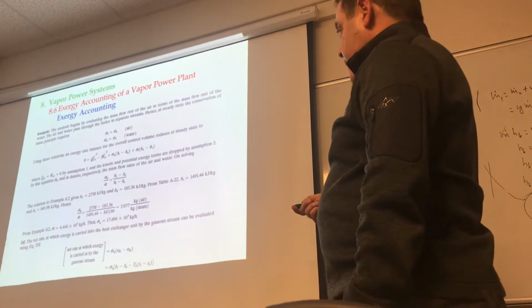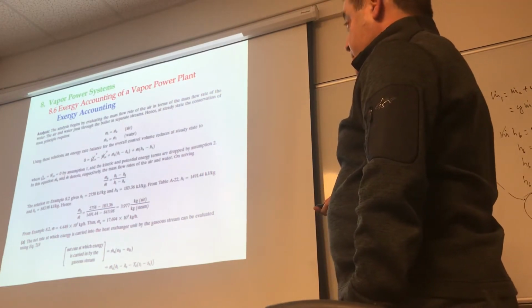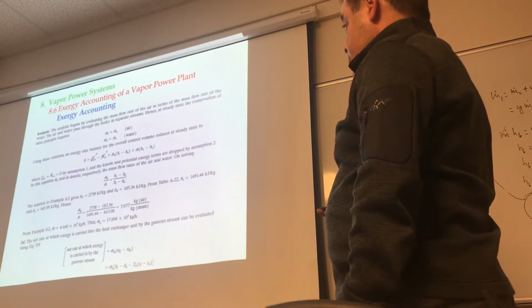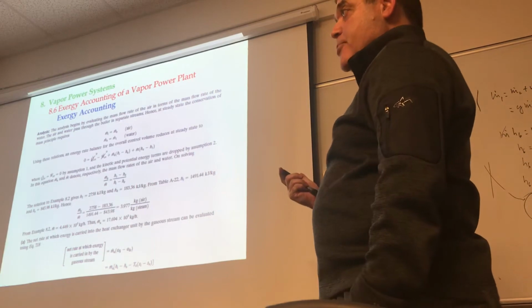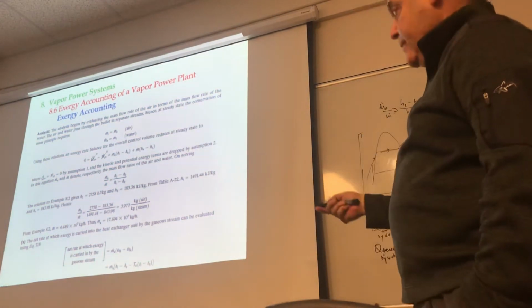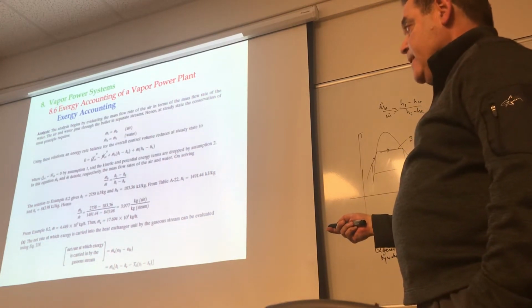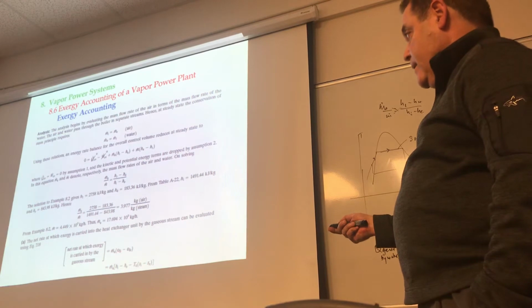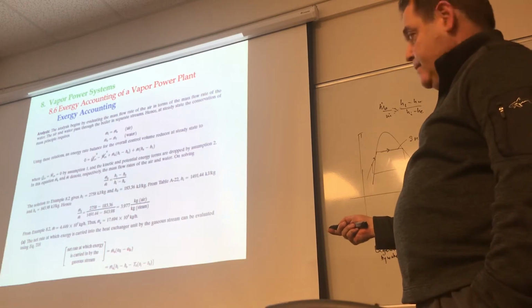Now, what is the net rate at which exergy is carried into the heat exchanger? So what brings in exergy? It's obviously the air, the hot air, right? So we're going to say it's the mass flow rate of the air times the flow exergy in minus the flow exergy at exit.